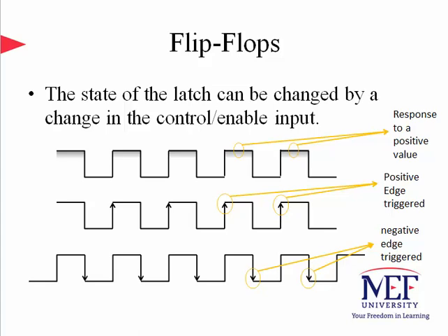However, while the latch is active and inputs change due to some other combinational logic, the state of the latch will change, producing multiple outputs at the given clock or pulse width. This creates a serious challenge and unpredictable outcomes for synchronous logic circuits. Due to this unreliable operation, latches are usually not used to design memory elements.